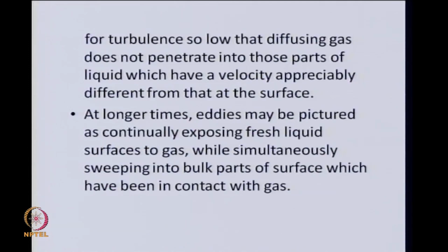So, if longer times come into the picture, total time is still short enough to guarantee unsteady state conditions, but the depth of penetration is now sufficiently large such that the diffusion can actually be seen by that region of liquid deep within, where the velocities are very different from surface velocities.